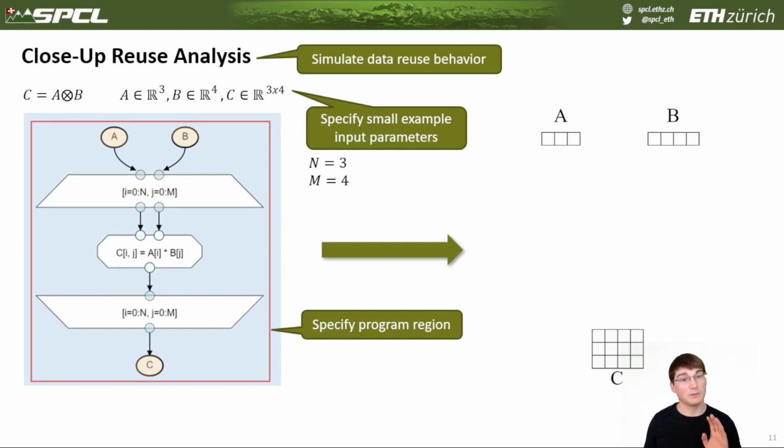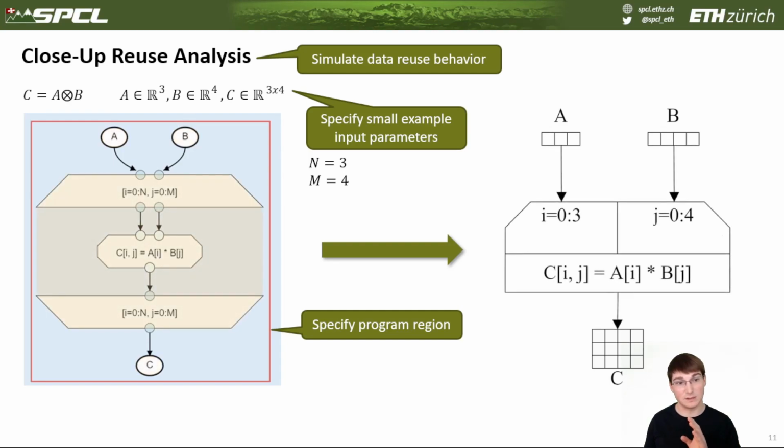But not only can we parameterize the data containers, we can apply the same technique to parameterize the parallel regions. Because we have parameterized the input parameters, we now know the exact intervals or bounds for each of the parameters to the parallel region. And so we can render for each of the parameters a slider that allows the user to select a specific value inside of the bound for that parameter.